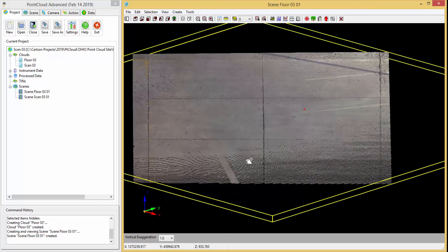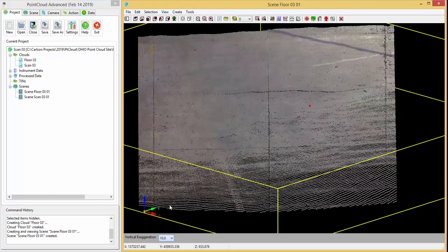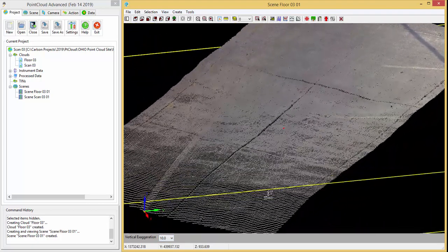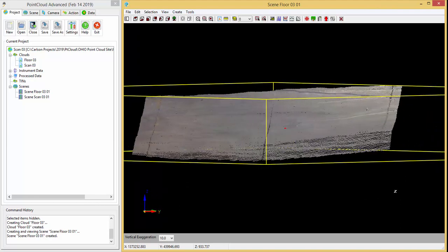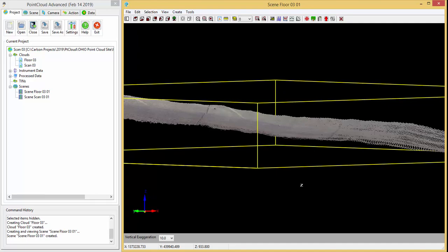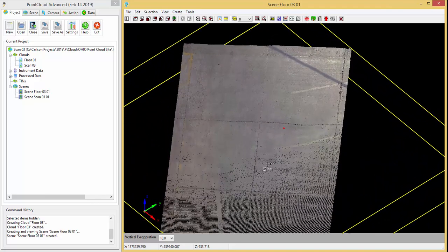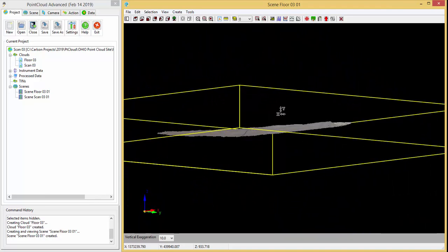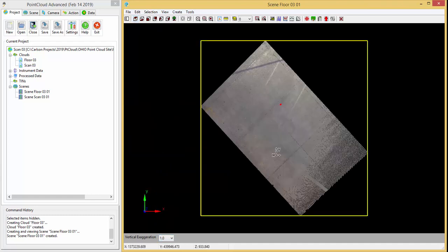Now, the reason why I am viewing this, I want to go to the vertical exaggeration down here and go to 10 to 1. Certainly looks flat now, doesn't it? Now, when I go to 10 to 1, you can certainly see it there. It looks like it actually undulates, so you can clearly see that at a vertical exaggeration of 10 to 1, vertically to horizontal, this sloping surface that looked flat actually has little undulations in it. Alright, we're going to go back to vertical exaggeration of 1 to 1, and set it back to plan view. Okay, let's make a grid file.